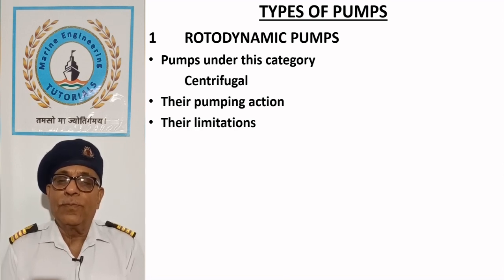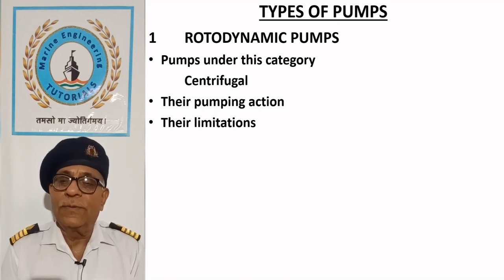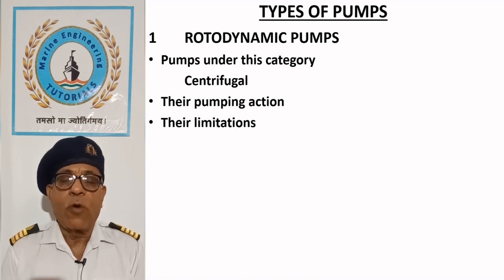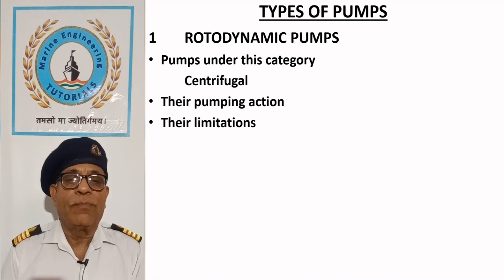As these pumps are unable to handle vapors, they may be equipped with a priming arrangement to remove air or vapors from the suction side when expected to draw liquid from a level below the pump, especially when the liquid is volatile in nature with high vapor pressure.